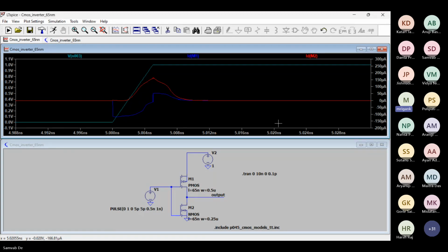Ideally, we can ignore the capacitance, but ultimately, CGS will lead to a small signal current flow from gate to source, because now the input is transitioning fast. If you look at the impedance of that CGS, for high frequency, it will allow some current to pass. As a result, that high frequency component passes from gate to source, and it leads to current in the opposite direction. It appears as if the charge is getting injected from the source.